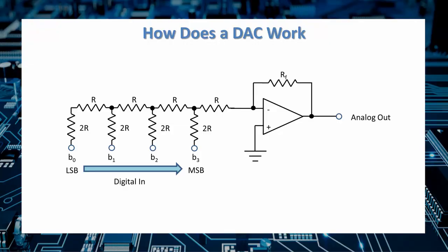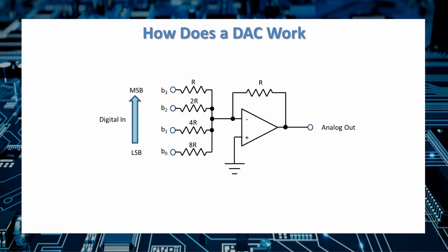A resistor network by itself isn't very good. What we really need is some way to buffer the output of the DAC. And to do that, there'll often be a buffer or amplifier on the output. Here's an example for the first resistor network topology we looked at. In this case, the feedback resistor can be used to control the gain of the amplifier. So it's possible to have a microcontroller running at 3.3 volts, but have the analog signal out be much higher or lower than the voltage that the microcontroller runs at. And here's how we'd hook up that amplifier in that second resistor network topology.